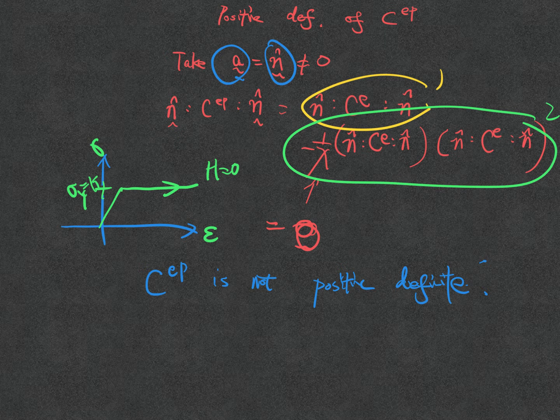Okay, so what happened to the strain-stress relationship? Okay, it's not 1-to-1, right? Isn't it? It's clearly not 1-to-1. Why is that? It's actually many-to-1, because I can have a strain here, and I will lead to this stress. I can have another strain here, I will also lead to that stress. Okay? So what it means is that if I know the strain, it won't be sufficient for me to know what is the stress. Does that make sense?